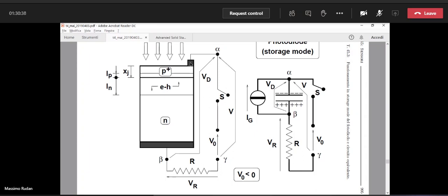So we have photons coming in. The photons enter the device, and you remember well, but we shall see it in a second in another slide, that there is an absorption, and this absorption has an exponential form. So the flux of photons decreases exponentially in the material. For this reason, it is necessary that the neutral region on the P side of the junction, that is the side on top of it, should be very thin.